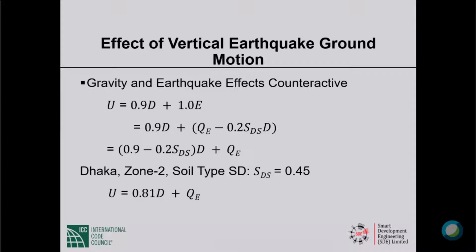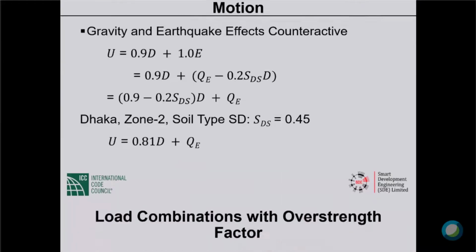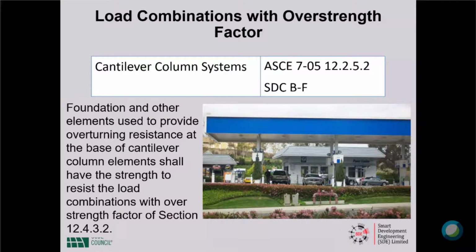So what I just discussed is extremely important. We do not have fixed dead load factors in seismic load combinations. The dead load factor is increased in the additive load combination by considering vertically downward earthquake effect, and the dead load factor is decreased in the counteractive load combination by considering vertically upward earthquake effect. Okay, then we go to a related but slightly different topic.